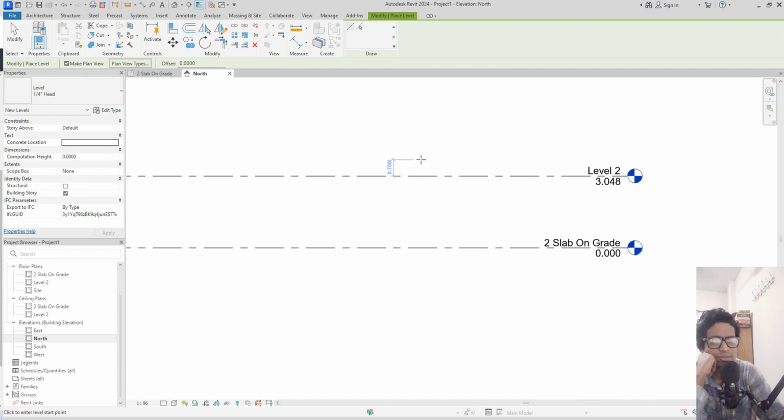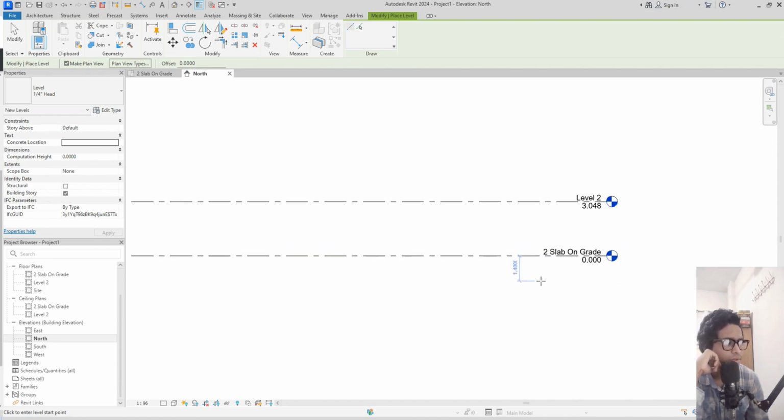Yeah. And the system families, I forgot to give you some examples: the slabs, staircase, curtain walls, partition walls. These are the system families. You cannot make these families. Revit made this for you. You are only allowed to add extra layers and regulate the thickness of these layers. You are allowed to do such things, nothing else. So yeah, this is all about three types of families.